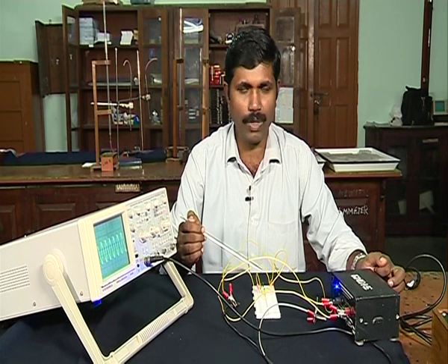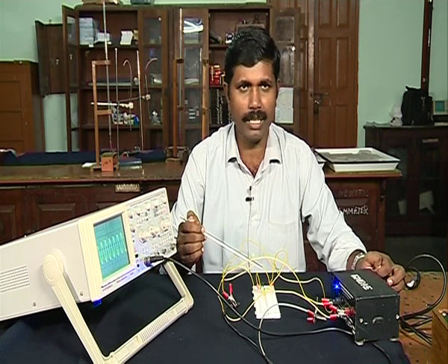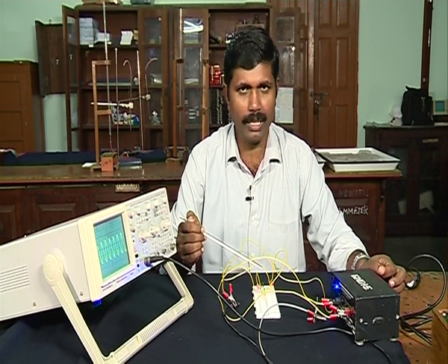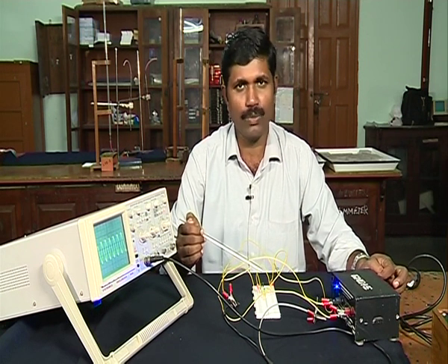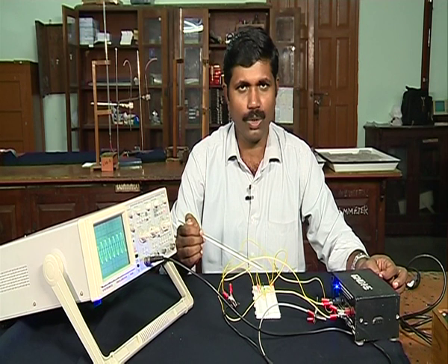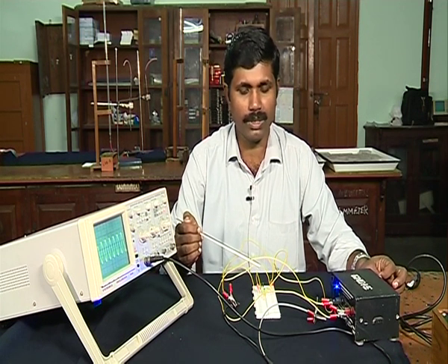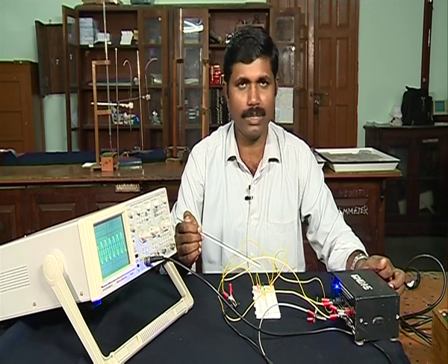So the output waveform is 180 degrees out of phase in this phase shift oscillator. A 180 degree phase shift is obtained by using 3 RC networks. If you use 6 RC networks, you can get a non-phase shifted wave which is possible using this phase shift